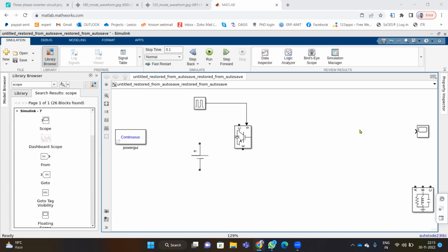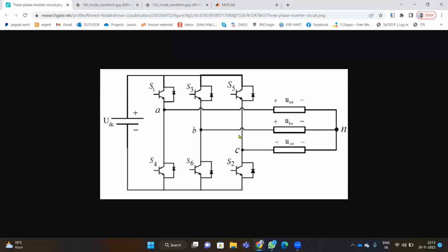In today's video, I will be discussing simulation of a three-phase inverter with you. We all know that in simulation of a three-phase inverter, we need to connect six controlled switches to which we can give the gate pulses. So six different gate pulses can be given to them, and a DC can be converted to three-phase AC with a star or delta connected load.